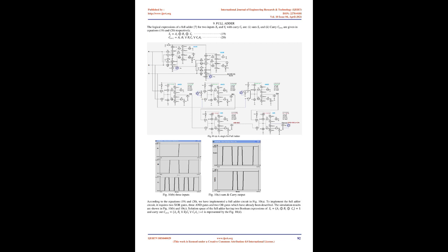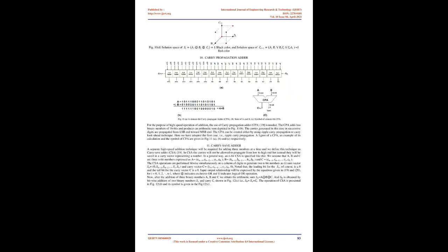On the other hand, the input signal vector elements 1, 2, 3, weighted by their respective vector element capacitances 1, 2, 3, are being subtracted from the voltage across the junction. The critical voltage is required to enable tunneling action, and it acts as the intrinsic threshold of the tunnel junction circuit. The bias voltage, connected to the tunnel junction through the capacitance, is used to adjust the gate threshold to the desired value. When a tunneling phenomenon happens through the tunnel junction, an electron passes through the junction from A to B, Fig 3.